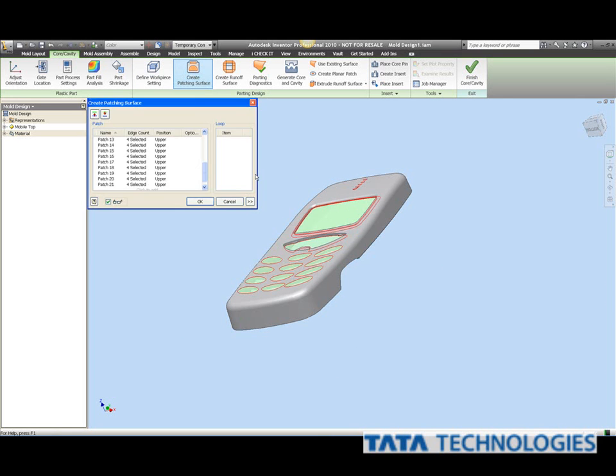In this case, we can see it's generated a list of the surfaces it's patched for me along the way. In some cases, there are dual surfaces that we need to worry about. In this case, surface 3 and surface 4 are no longer needed. I'll remove those from my model and move on to the next area.